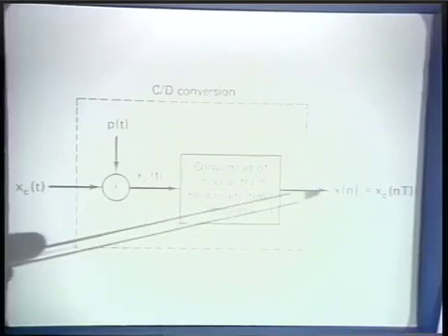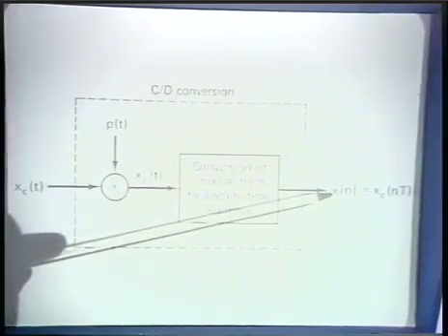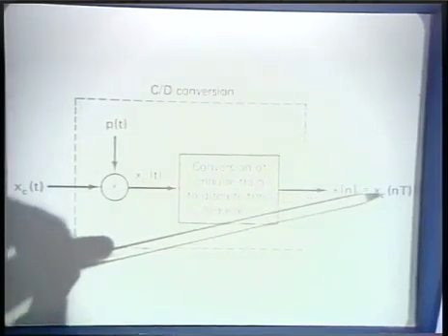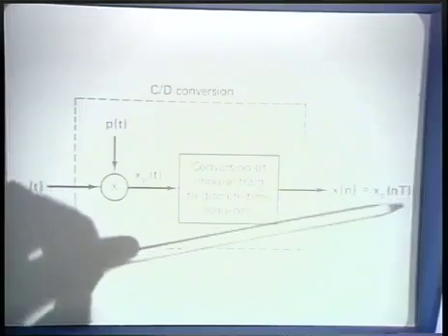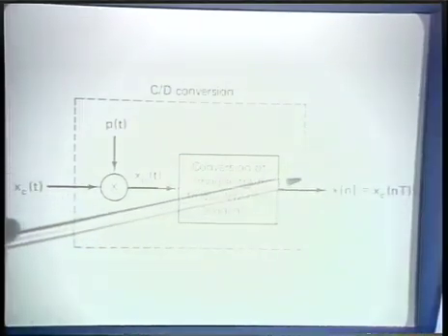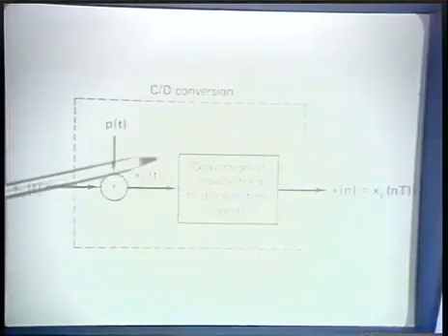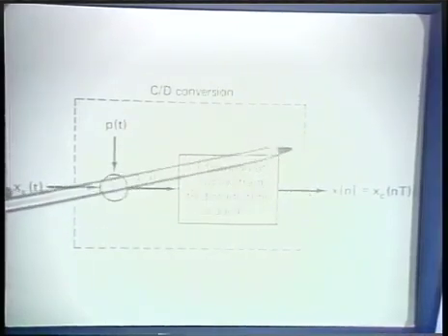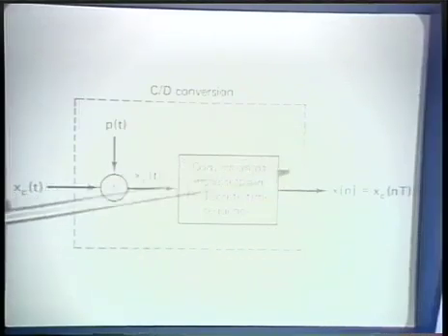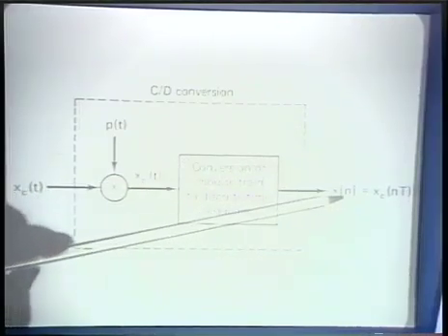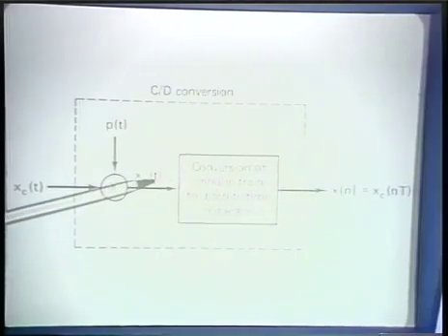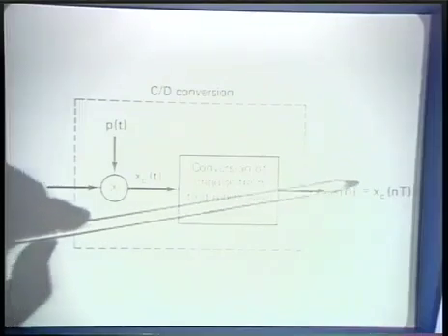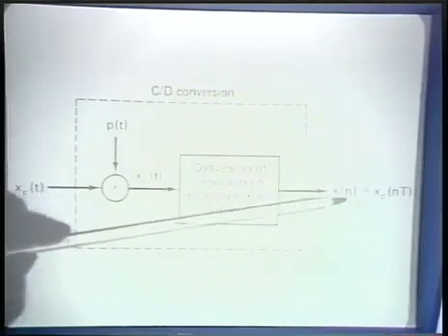And the discrete time sequence x[n] is simply then a sequence of values which are the samples of the continuous time signal. And as we'll see as we walk through this, basically the step of going from the impulse train to the sequence corresponds principally to a relabeling step where we pick off the impulse values and use those as the sequence values for the discrete time signal.